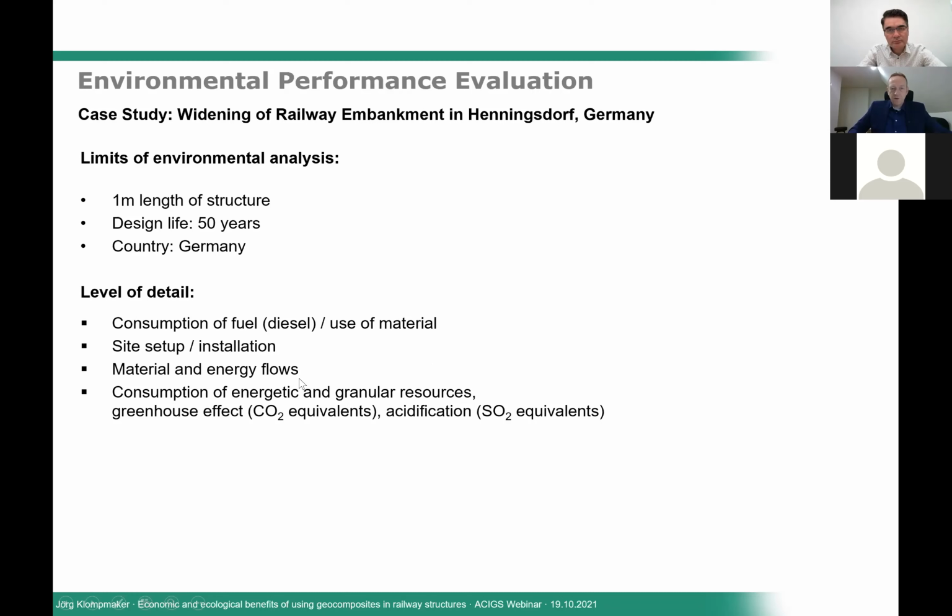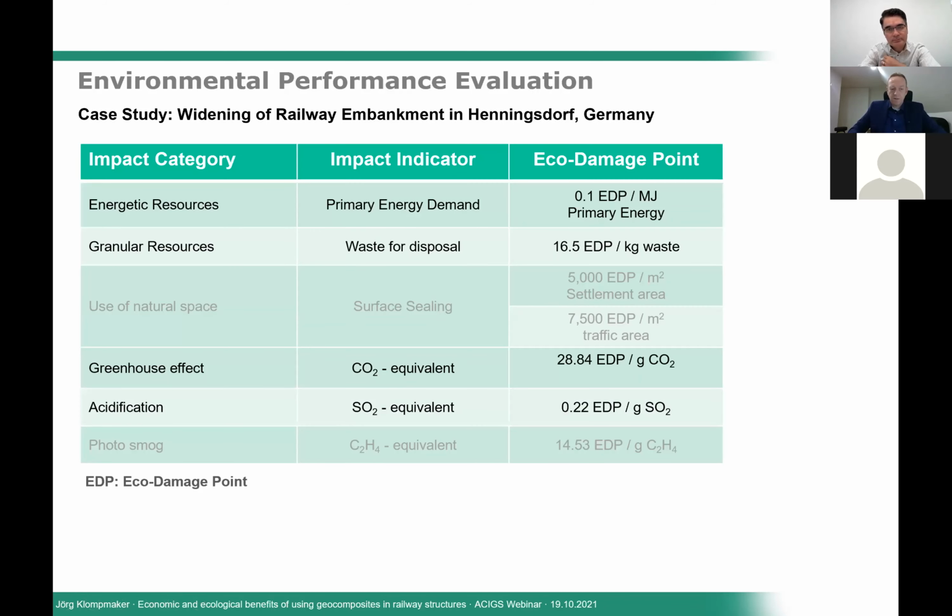Material and energy flows were considered, and also the consumption of energetic and granular resources, meaning all the energy and granular fill materials required to construct this reinforced soil structure. The greenhouse effects were quantified as CO2 equivalents and acidification as a result of the construction works in terms of SO2, sulfur dioxide equivalents were calculated.